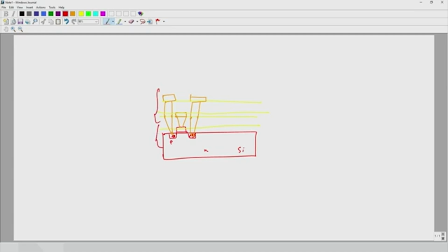What we mean by front end is the doping region and the critical active layer, just below the contact and gate. This is called front end of the line, FEOL. And then all the metallization and the connectors that we do is called back end of line. These connectors are very important to connect various transistors.